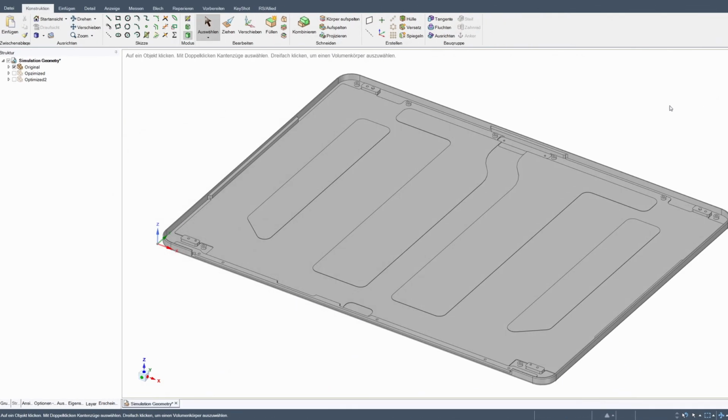Now I've created a new file containing only the 3D model of the lid. What we'd like to do now is simplify this geometry as much as possible. This step is not mandatory, but it will definitely save us some time and computational resources later on in the calculation stage. By deleting these details now, we can reduce the size of the mesh that we will create in